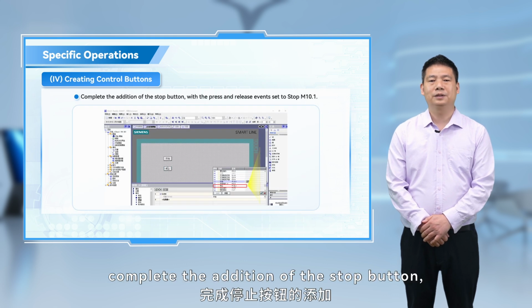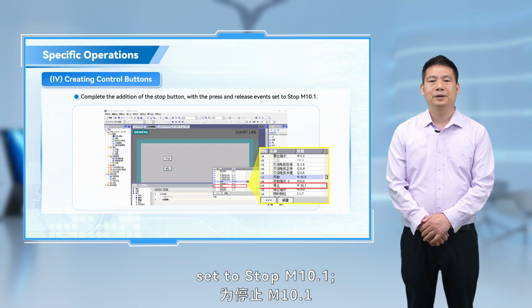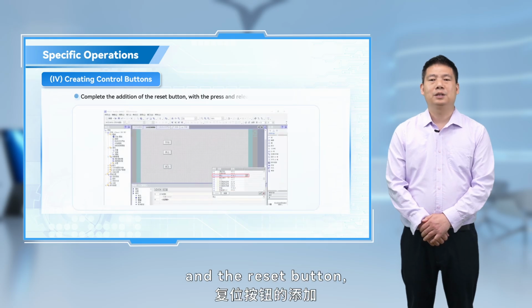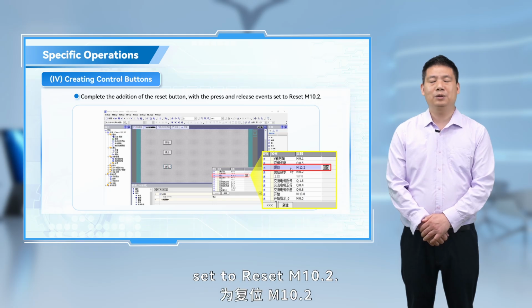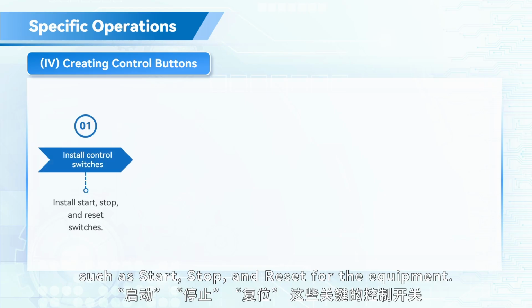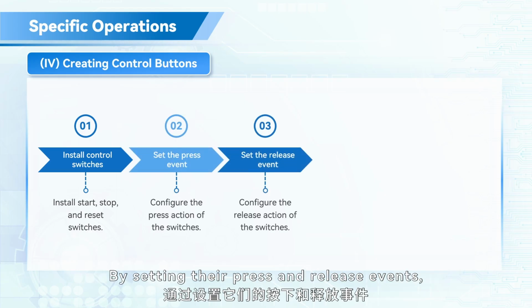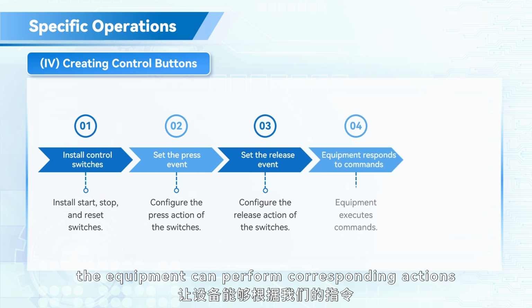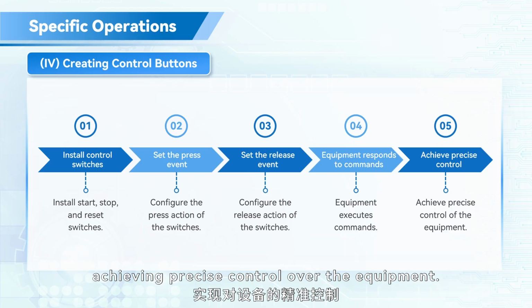Similarly, complete the addition of the Stop button, with the press and release events set to stop M10.1, and the Reset button, with the press and release events set to reset M10.2. This step is equivalent to installing key control switches such as Start, Stop, and Reset for the equipment. By setting their press and release events, the equipment can perform corresponding actions according to our commands, achieving precise control over the equipment.